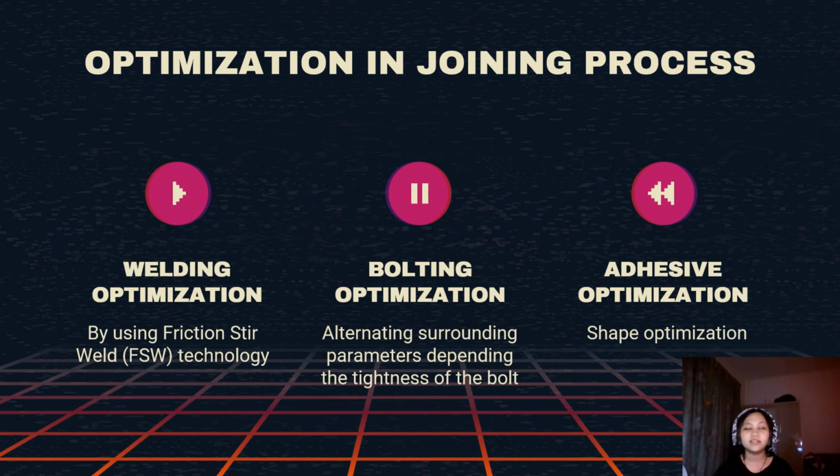By using this technology, it reduces defects as it provides almost none of the hot cracking, porosity, or solidification cracks. It also reduces shrinkage as FSW technology uses low temperature to join two workpieces together. No filler material also means savings in terms of cost and waste material, thus making it a good option to optimize the welding processes of these aluminum frames from earlier processes.